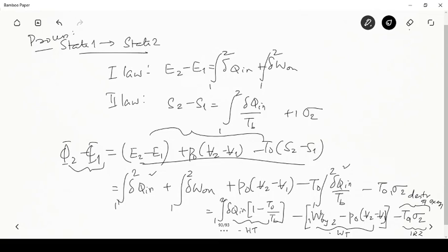And in the same fashion, now this minus W by, if work is being done by an object which is colder, then its exergy goes further down, so it goes away from the dead state. So this is negative. If the work is done by the object, there is a loss of energy.